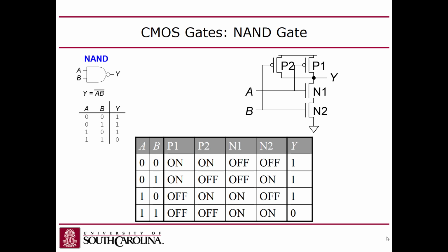So we got these two guys, which reduces down to not A and C, and then this guy goes like this on the Karnaugh map, and we've got not B and C, right? With me?